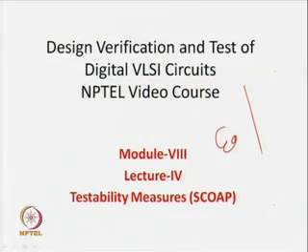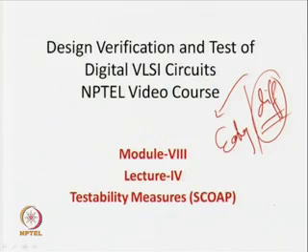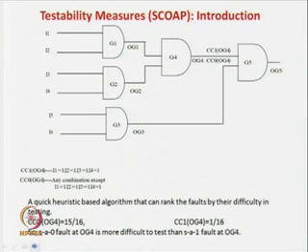So, we thought that if we can find some algorithm or heuristic that can say which are easy to test faults and which are difficult to test faults, then these difficult to test faults will not be brought into the paradigm of random test pattern generation. We will try only the easy to test faults, and keep the difficult to test faults in a separate bin and go directly for the sensitize, propagate and justify approach. This will help in optimizing the random test pattern generation algorithm, because we will not be trying, in every iteration, the faults that linger because they are difficult to test.